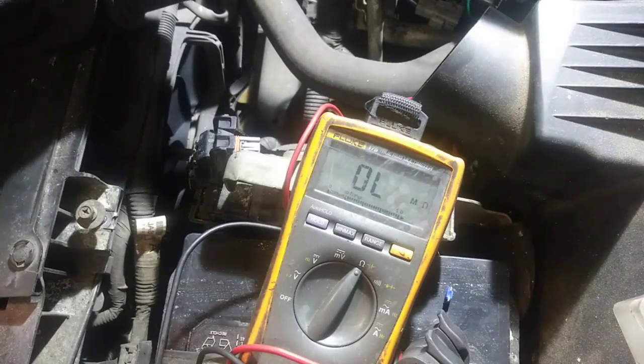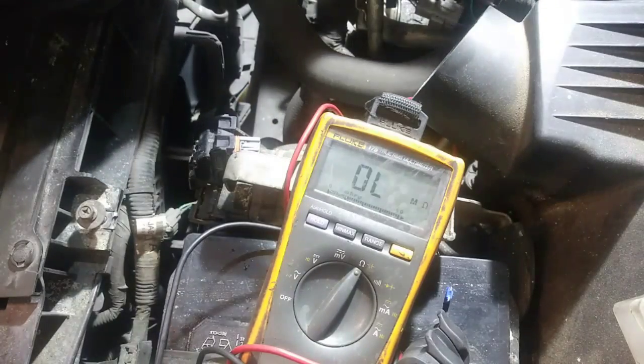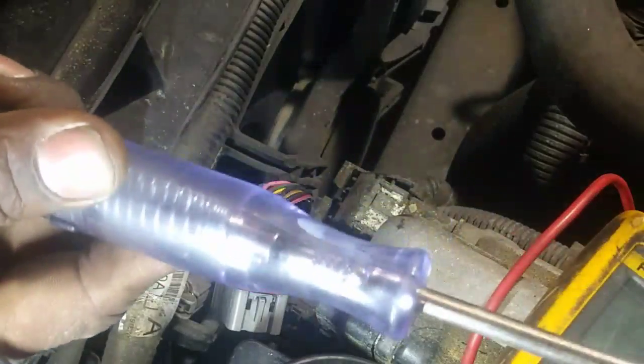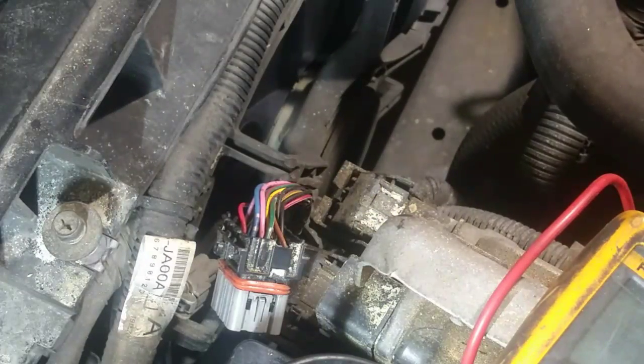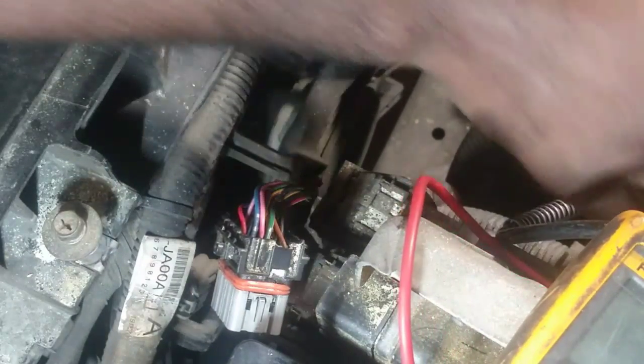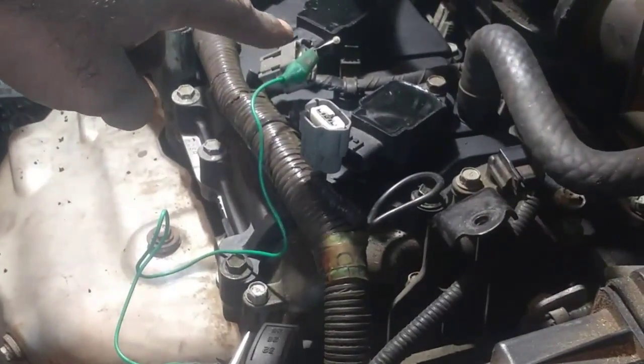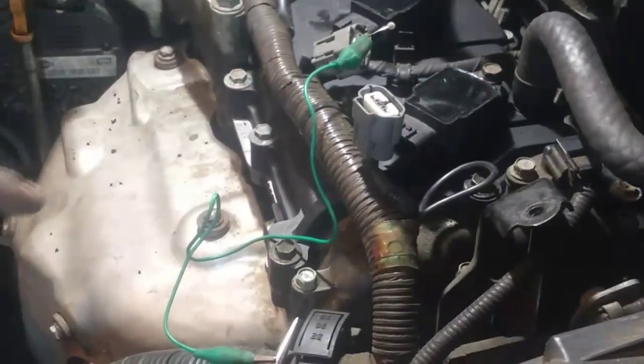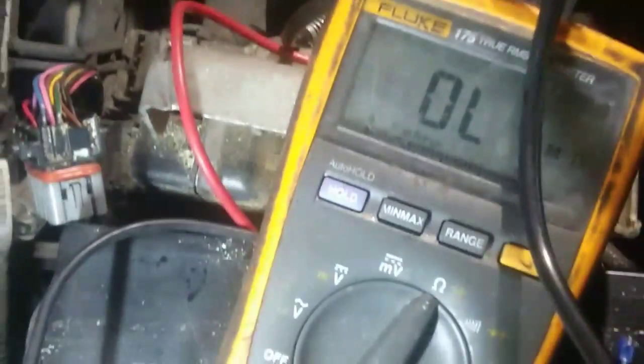I'm going to hook it up to the working one, and that is open also. I'm going to use 2 test lights. I got one here, which is going to go to battery positive, to my alligator clamp here. So it'll look like this. I have my alligator clip on battery positive, and there's my test light going to the wire that I'm looking for, and then I'm going to